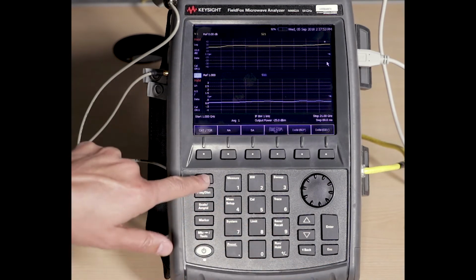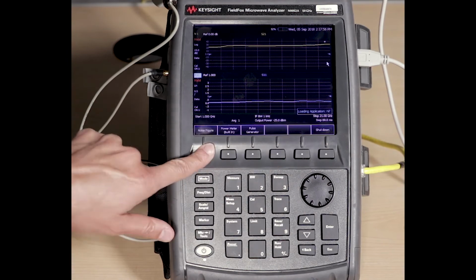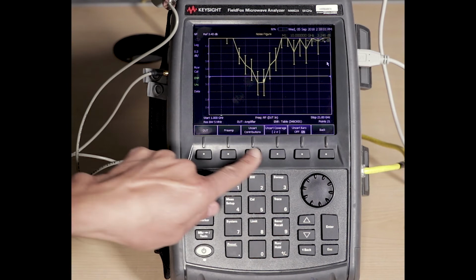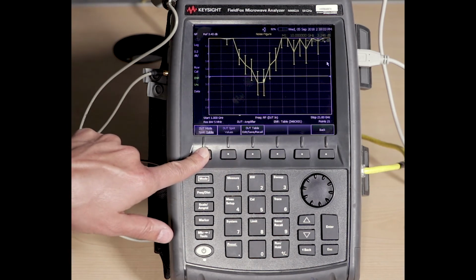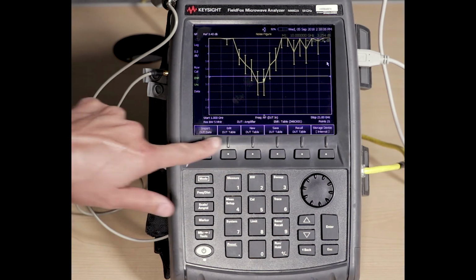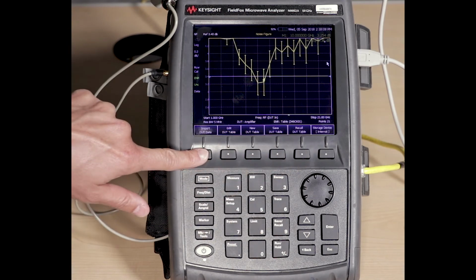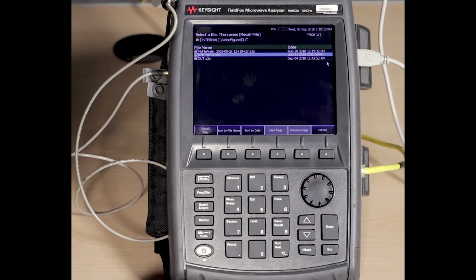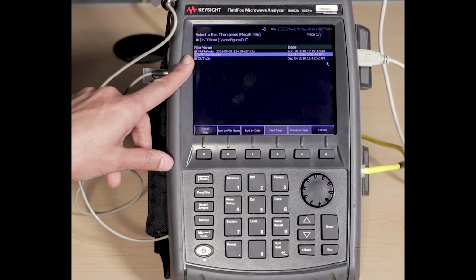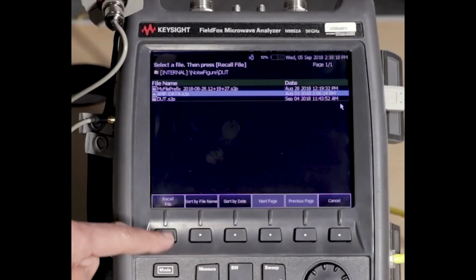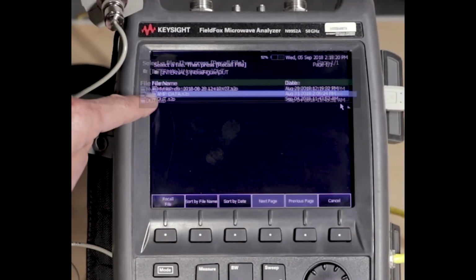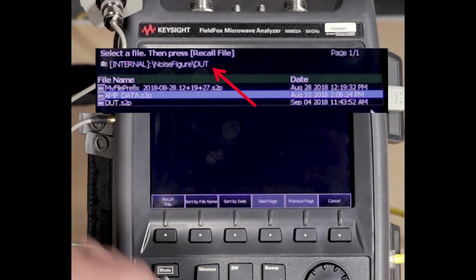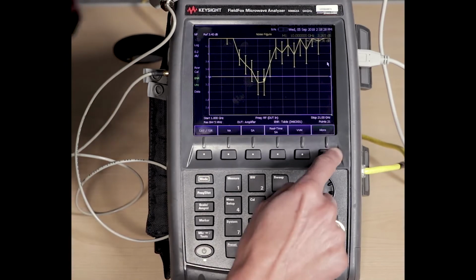And then you come back into your noise figure mode. You go to mesh setup, uncertainty, DUT, edit table, and it's not recalling, but it's importing. It says import the DUT data, and here I had to save the amp data as S2P, and I can pull it in, and that fills up my table. I want to point out that this amplifier data is in this noise figure DUT directory, so that's where it's saved. If you, in NA mode,